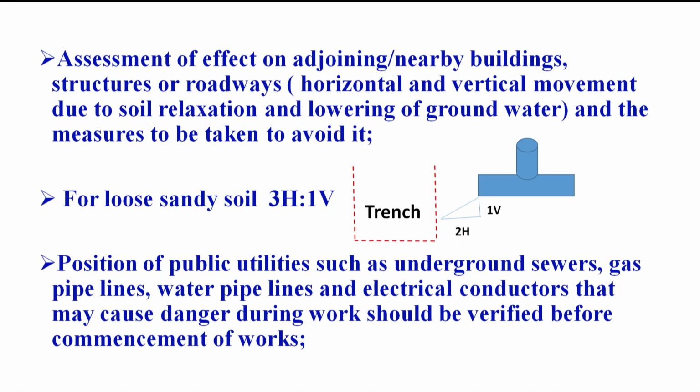So as I told you, for loose sandy soil, this load distribution occurs 3 horizontal to 1 vertical in that area, and otherwise we have to be very careful, up to 1 vertical to 2 horizontal. It means if we are excavating 1 meter deep, then we have to take proper care that our trenching or digging or excavation is at least 2 meters away from that adjacent building.